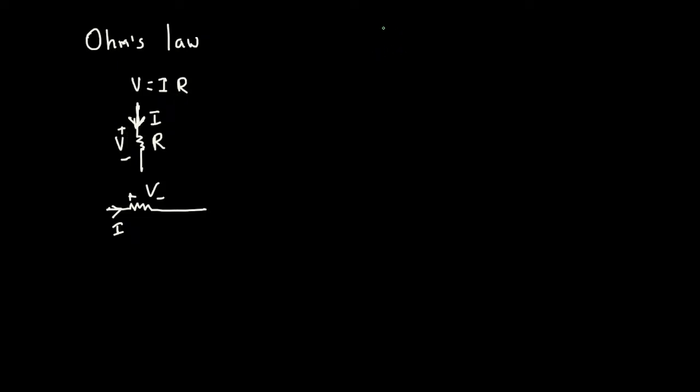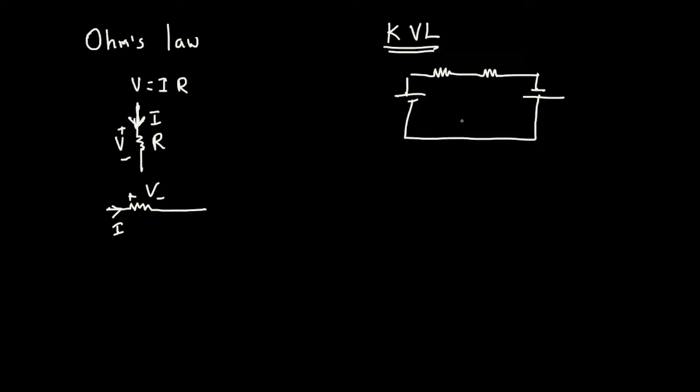And then the Kirchhoff's voltage law, you can also shortly say KVL. This one says addition of all the voltage in a loop is equal to 0. For example, if I take a circuit like this, here if I put some resistor and let's connect another voltage source, and this is a loop. Okay, here let's call this voltage across this as V1, and let's call this voltage across this as V2,